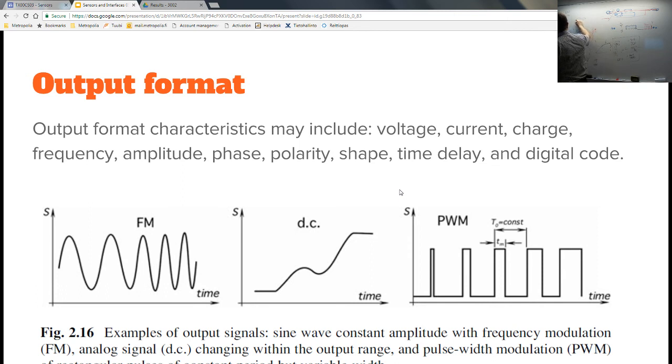It is fixed on this location, on a special glass, and those are the platinum wires, very close to each other, almost touching, not quite touching, but almost, meaning that there has been a wire which has been just lasered off. Temperature is actually changing the distance enough to be measured. So that actually also is a capacitive sensor.